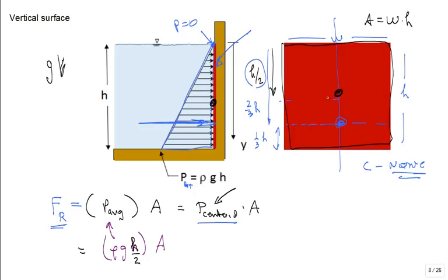But if you start to change the shape of the area, it pushes the centroid down a little bit. Okay, just like I mentioned. But it's still, to get the average pressure for this planar surface, just get me the centroid of that planar surface, then get me the pressure at the centroid. Okay? Then multiply that times the area, I have the resultant force.